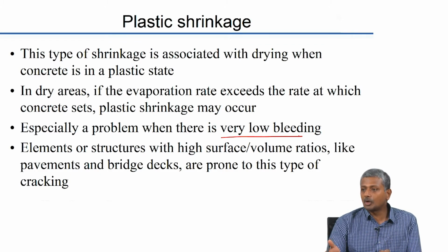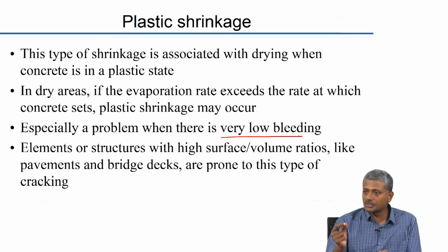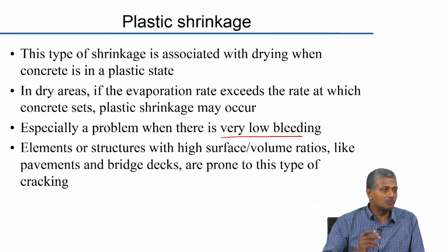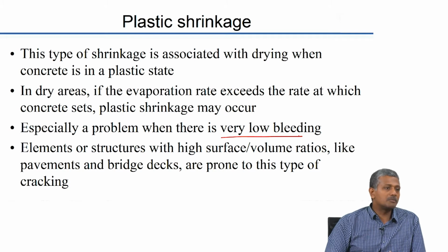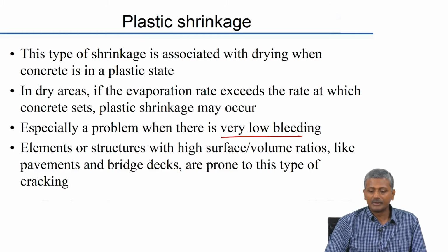Silica fume concrete, we talked about that previously also. The extent of pressure, the capillary pressure that gets generated upon drying, when you have extremely fine pores because of silica fume usage, that can really cause a lot of cracking in your concrete. So, silica fume concrete can be especially prone to plastic shrinkage problem. Of course, not all structural members will have plastic shrinkage issues, only the ones which are exposed or which have large exposed surface areas like slabs will have this issue.